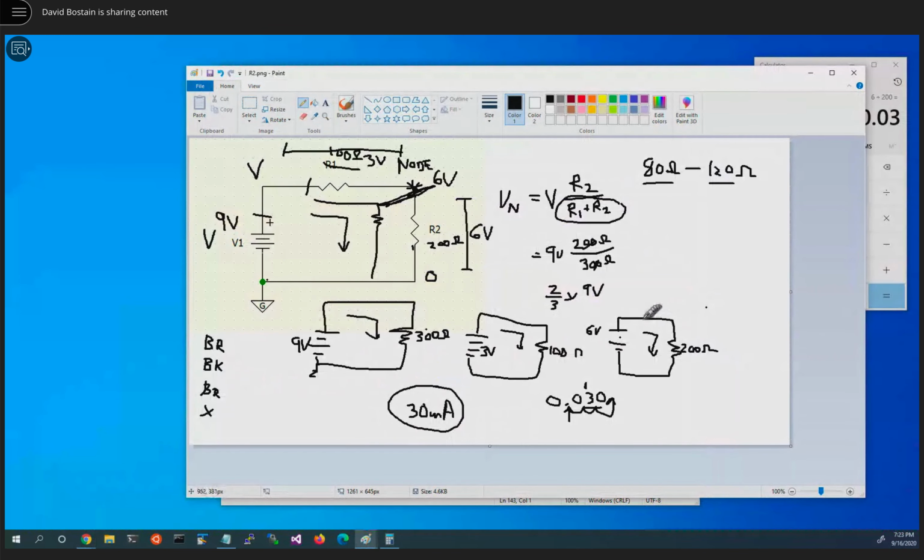How much wattage would we be burning? How much would the resistor be using up if we were to have it at its minimum or maximum value? Well, we'd have to do the resistors independently. We can't do it on this and get any meaningful data for this purpose. So we couldn't do it on the 300. So we have to work the power problem twice.